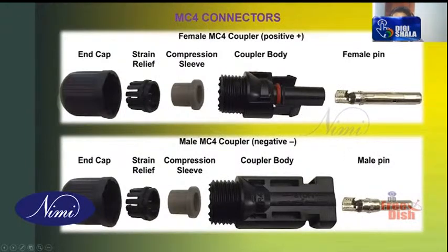When the cable comes, the cable can be crimped into this pin. So it should be inserted in this one. Once it is crimped, you cannot use this connector afterwards. It is a permanent fitting inside the coupler body. So the wire can be crimped here. This wire will go inside, and when it is tightened, you will get a solid protection type female and male part.